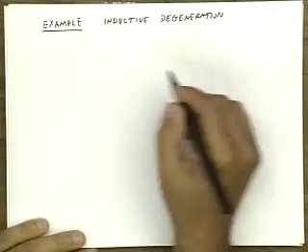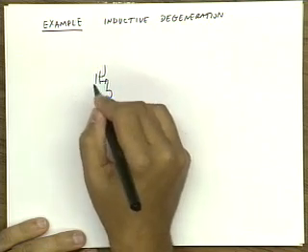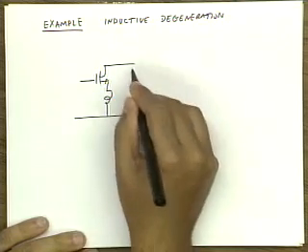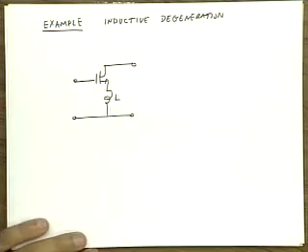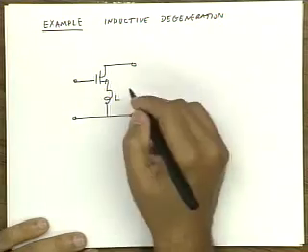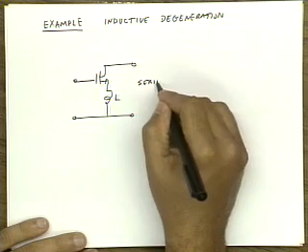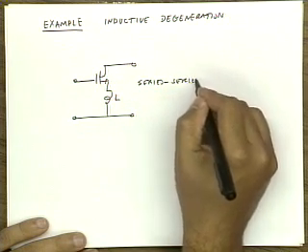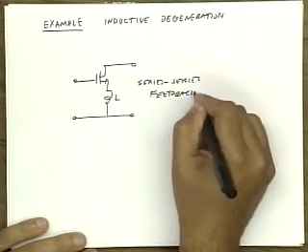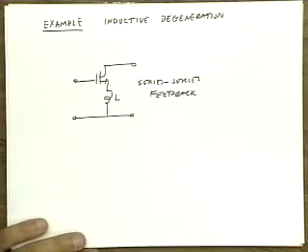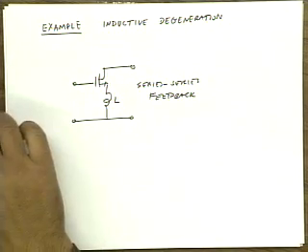If you look at RF amplifiers, you'll often see a basic building block, which is this. So it's our basic transistor, but it uses an L as a degeneration. So this is a series feedback, series with the input, series with the output. And so the question is, first of all, what's the effect of doing series feedback? What are some of the benefits? We'll see that throughout our analysis.